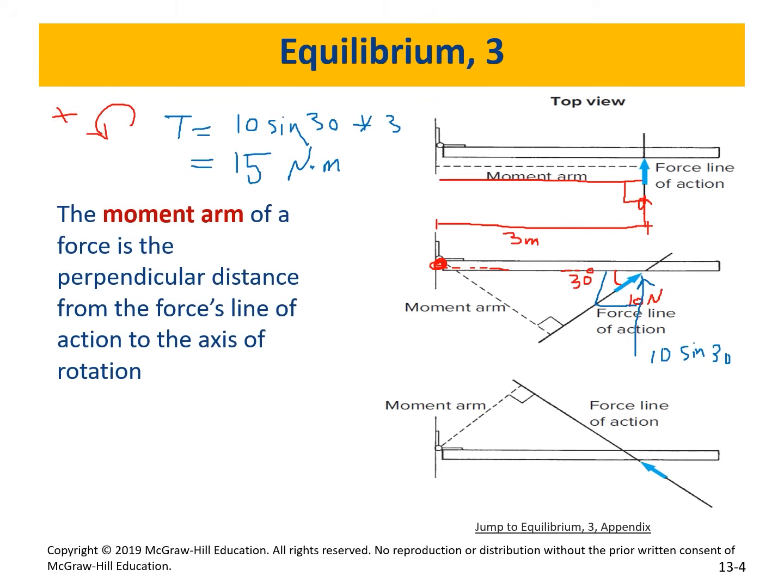So if you have a force with an angle, you need to resolve it into the x and y component, and then find the distance, and then you multiply these two. The one that is perpendicular to the moment arm is the force that matters. Make sense? We good? Okay.